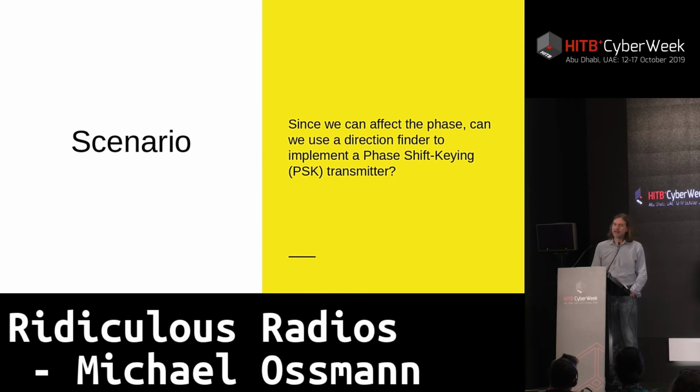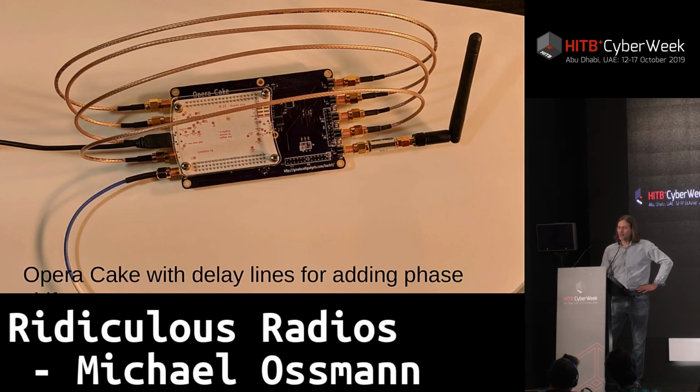Because if he can do that, then he can actually create a covert channel. He might have his Bluetooth dongle transmitting using frequency shift keying or on-off keying or some other technique that it maybe natively knows how to do. But then he can also add a hidden layer of modulation on top of that signal. We thought that was very interesting, and kind of a way to create a covert channel on top of a radio signal that you might be normally using or allowed to use.